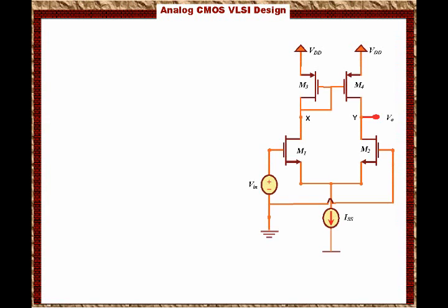The second approach to find the AC gain for the circuit is using the half circuit analysis. Remember that transistor 1 and transistor 2, M1 and M2, are symmetric and they have the same source, we called it VB, and the AC voltage at the source is assumed to be 0 if the input voltage is divided in half between the two nodes.